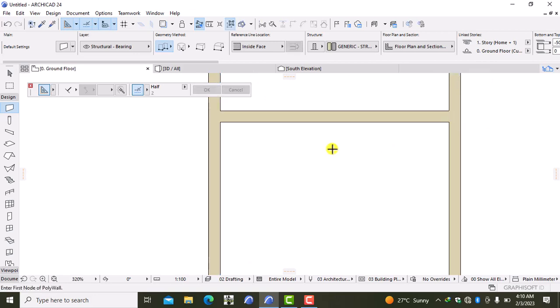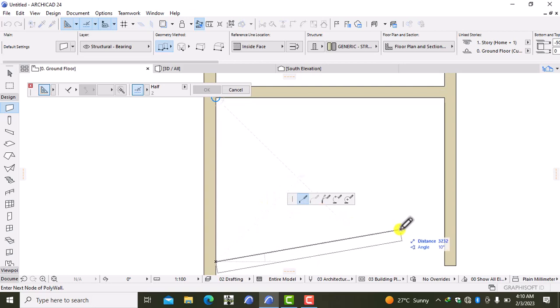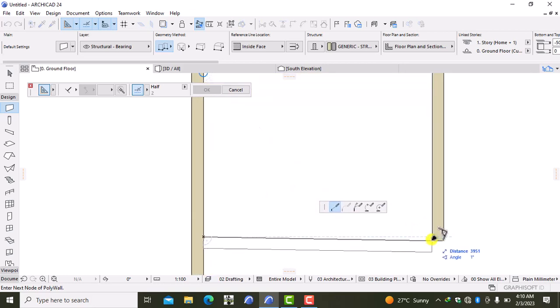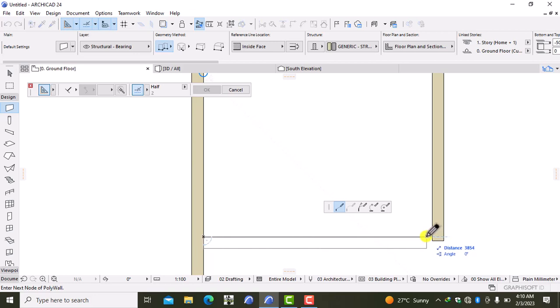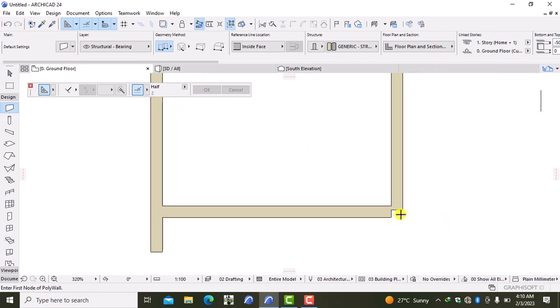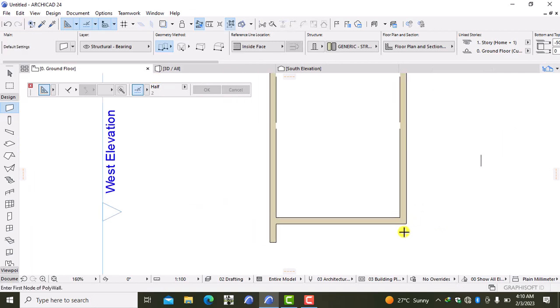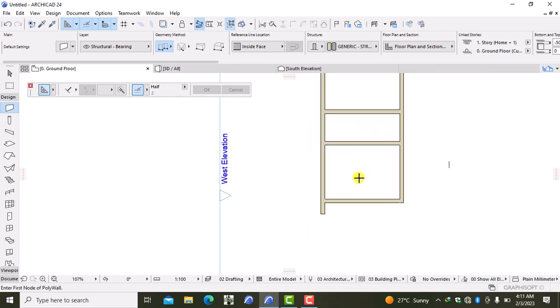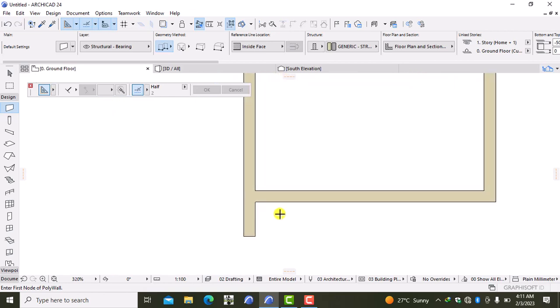And I'm going to drag this particular wall over here. I want to do another wall from this particular point, a distance of 2900. So you might be wondering why this particular room is going to be kind of smaller compared to the one we have done up there. The difference is you can decide to use this particular room as the guest room, and the guest room doesn't necessarily need to be that huge, but I'm going to work with that.